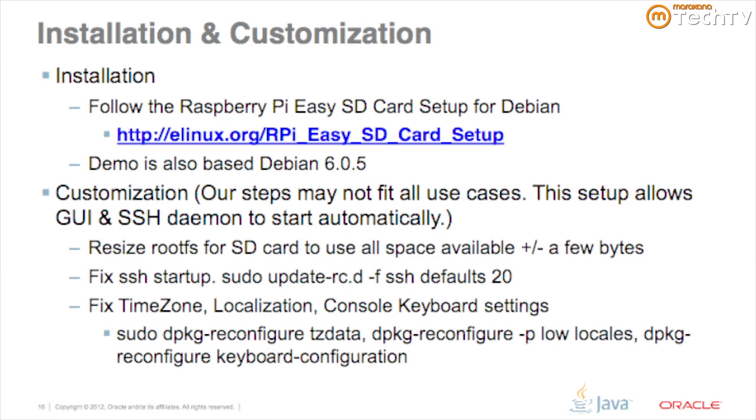So that's the resize. Next is the fix for SSH. I found that whenever I get an embedded device from any one of the communities, like Linaro, Ubuntu, or Debian, usually they already have a pre-canned image that you can pop onto these devices. Well, this is the first device I've got from somebody that didn't have SSH enabled. And I understand why. They didn't want to consume more power, more space, or use more memory, so they didn't start the graphics environment, and they didn't start SSHD. That command will tell you how to launch SSHD as an upstart job, and then you don't have to do anything. I've heard of a lot of people trying to install SSH, and wait, it's already there. That just shows you how to enable it.